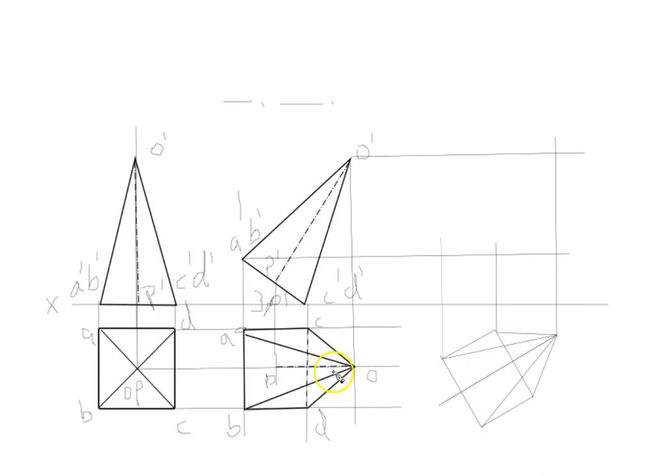base. Then you can also take the distance OP, and from this point to this point you can mark that, and completely join and create the tilted condition. The only thing is, you draw the axis with respect to the required inclination, take the points, mark the points on the divider from the earlier view, and simply transfer them here. So this is how you draw the tilted condition.